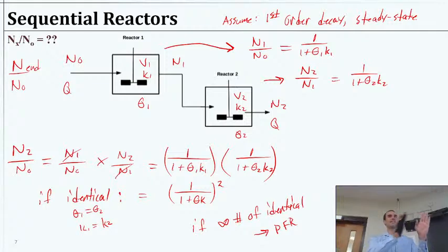It just acts the same way. It's a different mathematical way to get to it, but it will yield us the same exact equation that looks like a batch reactor just floating along across a conveyor belt through the system. So I don't really need you to know that derivation or anything, but it's kind of a neat look at how the math will work and why we can derive a plug flow reactor in a couple different ways to say it can be at steady state with flow through. You just have to have an infinite number of these little ones, this one's mixed, got flow going through it into the next chamber, it's mixed. That's pretty much the same exact situation as a plug flow reactor.